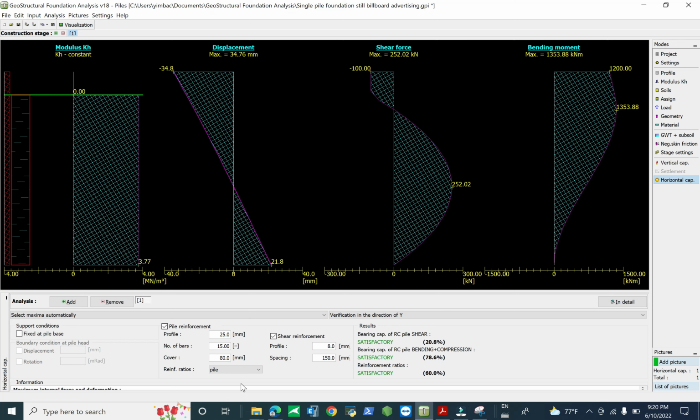If you use the same as column, the percentage required for the minimum in column is higher than for the pile, because column has no restraint from surrounding soil springs against the lateral displacement. But for the pile, we include the soil subgrade reaction to reduce displacement. It is also designed as the restraint.